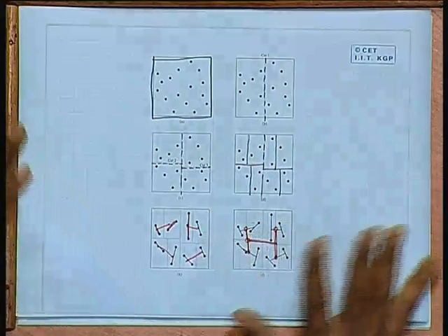If you do this, the clock skew will be less, not zero. You are not trying to make it zero here. There will be clock skew, unlike the H tree algorithm where the path lengths are equal, but here the path lengths are not equal, but you are trying to make a uniform distribution all throughout the chip, meaning how we can lay out the clock.